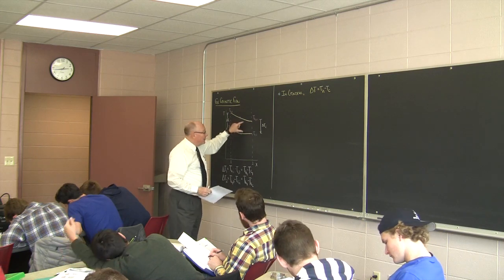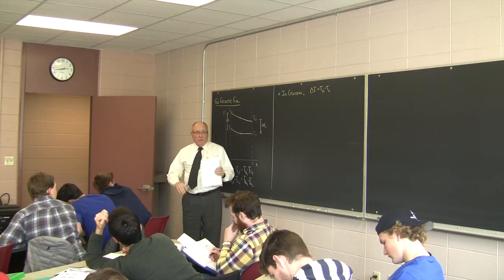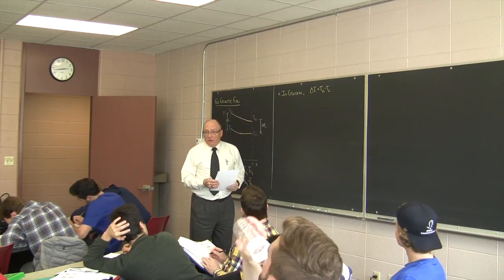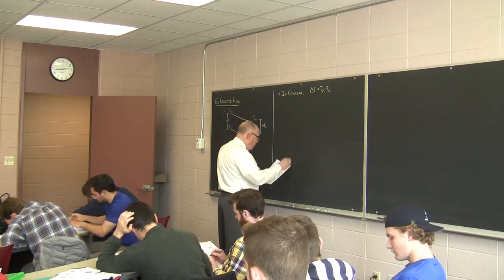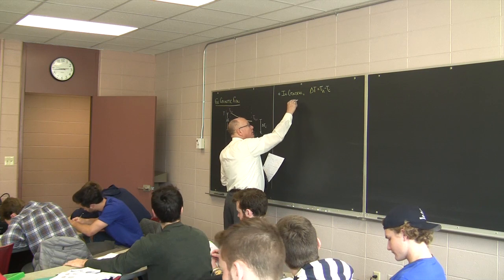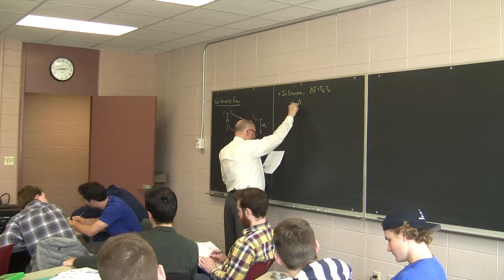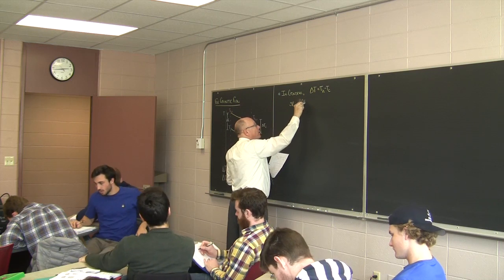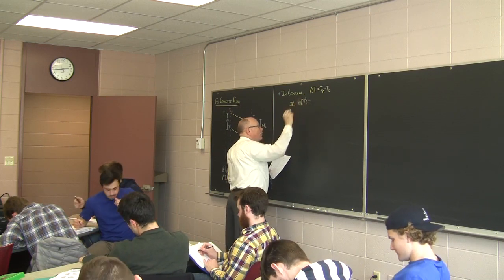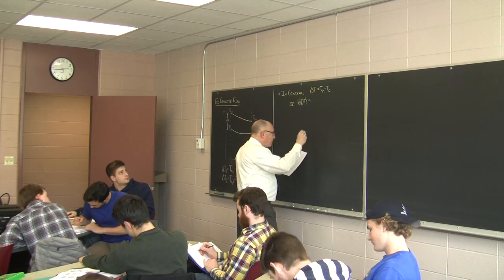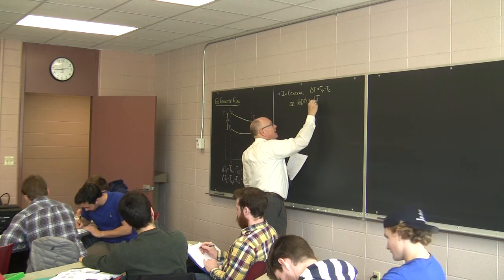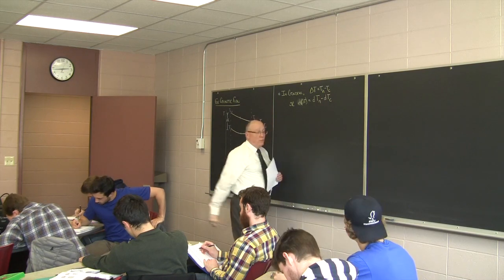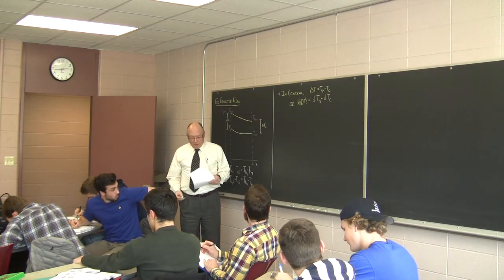At any point there's a delta T here, there's a delta T over there. We'll worry about identifying it in a moment, but this is a generally true statement. Or we're going to say that the differential change of delta T will be equal to the change in the hot temperature minus the change in the cold temperature, the differential change.